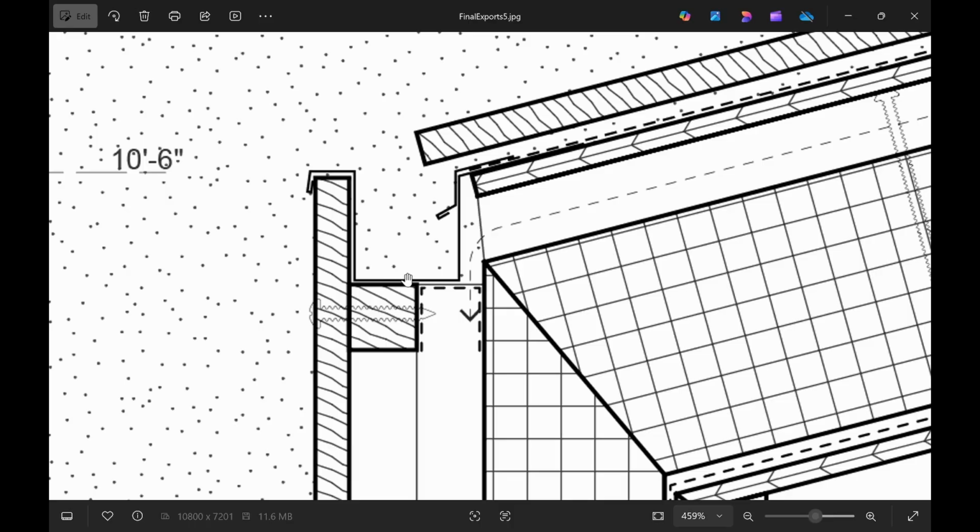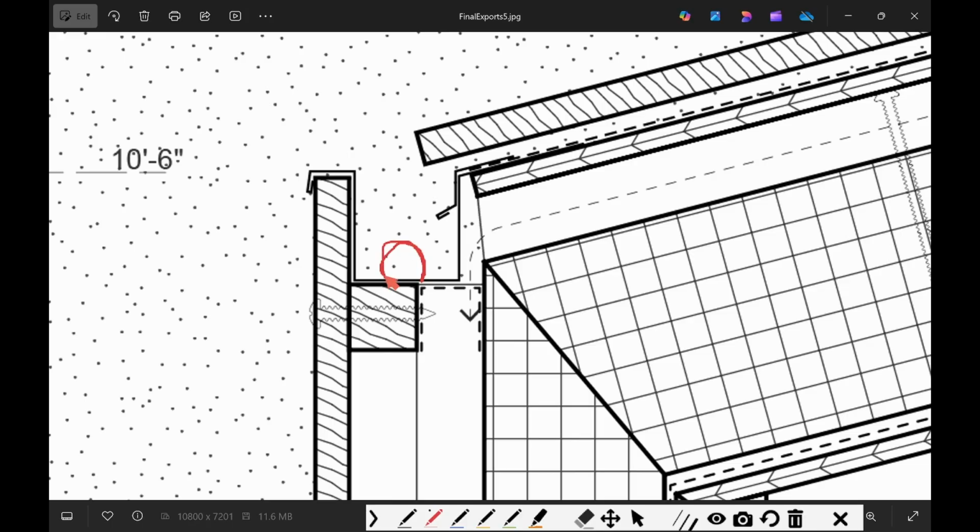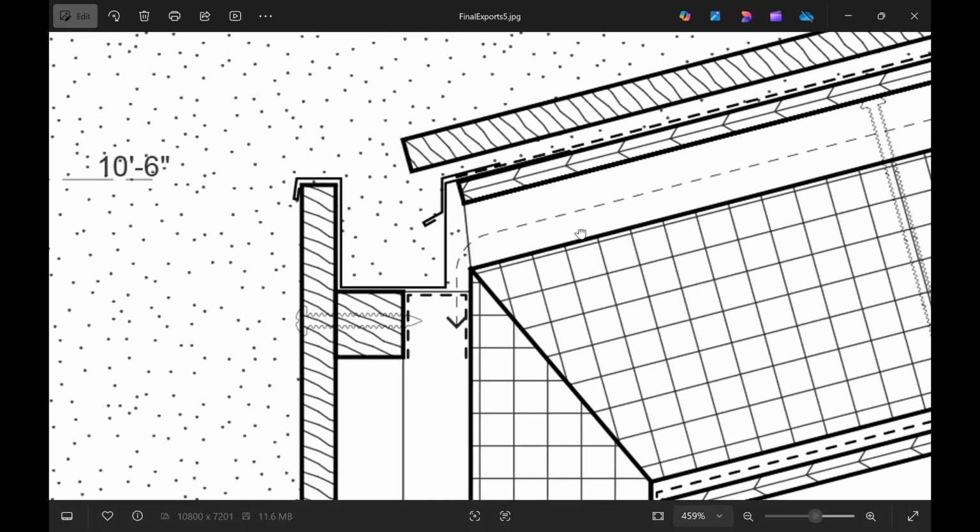One thing I could have shown in my detail is the downspout system, the filter of the downspout right here. You need some type of drain, unless you want to extend the gutter well beyond this so it shoots out from the sides. I should have shown maybe a dashed line of a filter in the gutter for the downspout that goes down in there. I'll explain the assembly of what's going on here, but I'll do it at the roof.